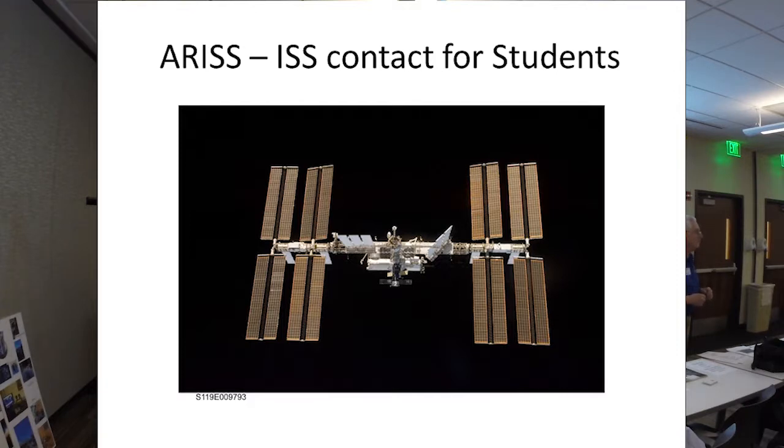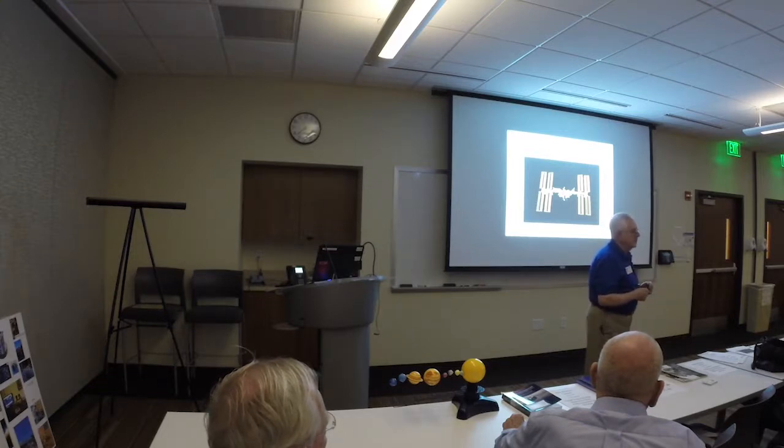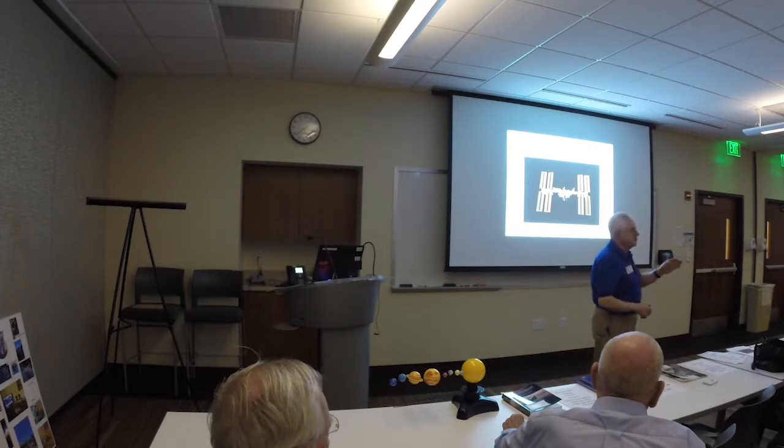That's correct. They are tumbling. Unless they have the CubeSat that I showed you that was in pieces, it had a magnet built into it. That magnet is supposed to keep it pointed at the Earth. But most CubeSats are tumbling, so they vary in and out. The recommendation by NASA is that you have a polarity switch, even if you have a left-hand polarized antenna that you're using, which means it has horizontal and vertical and horizontal. What they want you to do is flip back and forth so that you get the right sequence.